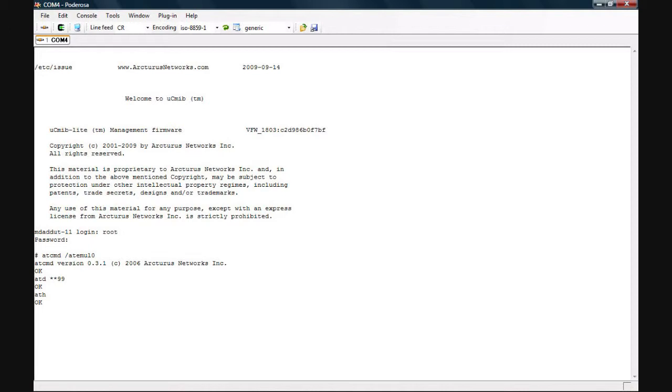There are control commands like the ones I just demonstrated, ATD and ATH. There are status or ATS commands, which can do things like determine the registration state of the device. There's feature codes like **99 or vertical service codes. And there's also progress messages that come back through the API to keep you informed of what the status of the session is. So I'll give you an example of that.